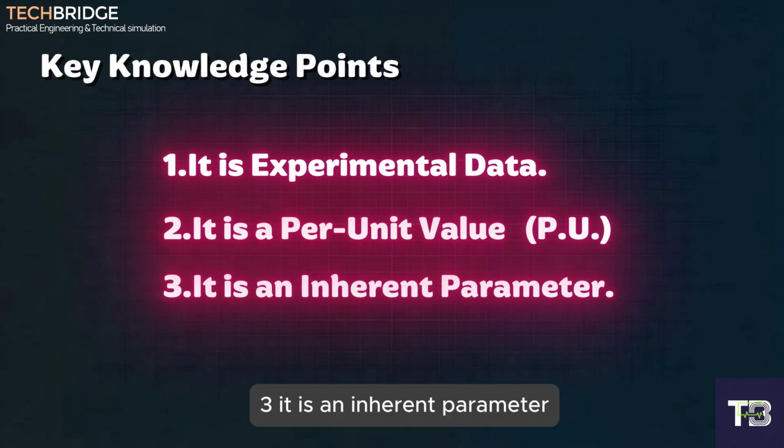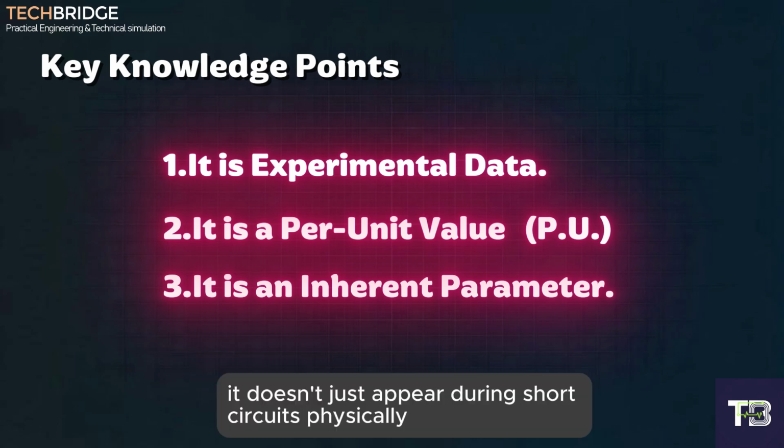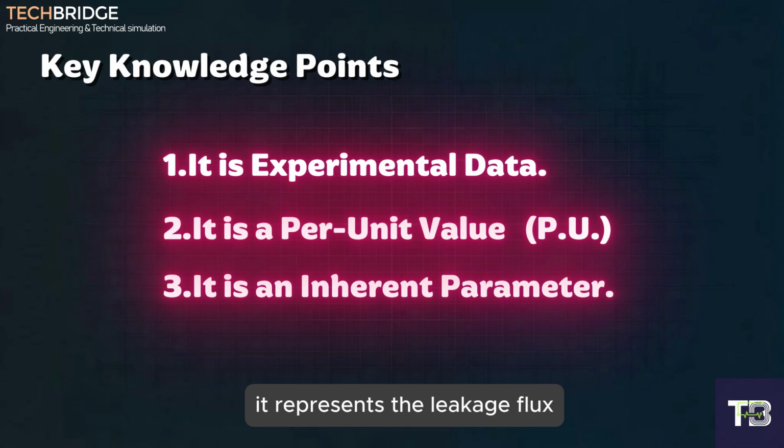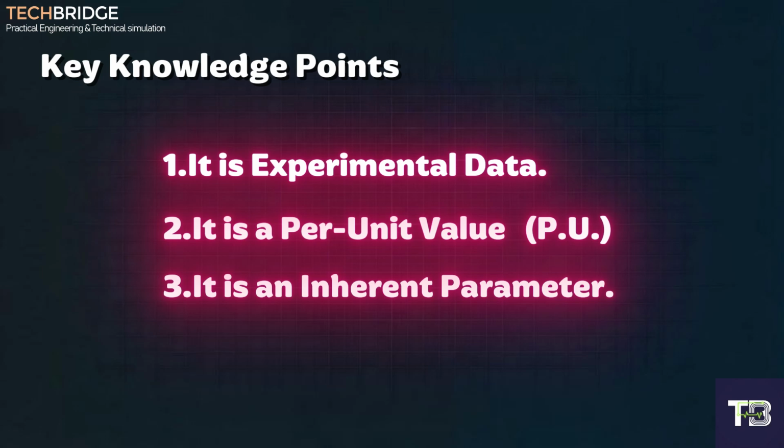3. It is an inherent parameter. It doesn't just appear during short circuits. Physically, it represents the leakage flux. It represents the internal voltage drop when the transformer is at full load.